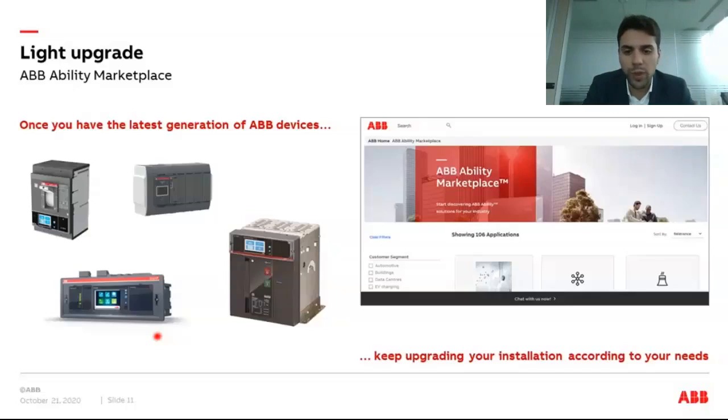An example: you want to monitor the power quality of your electric installation and you are using, for example, the Emax 2 or Emax XT circuit breakers from ABB, the latest generation. You can simply download the network analyzer function, upload it into your protection device, and immediately start to monitor the power quality, for example, even up to the fifth harmonic.